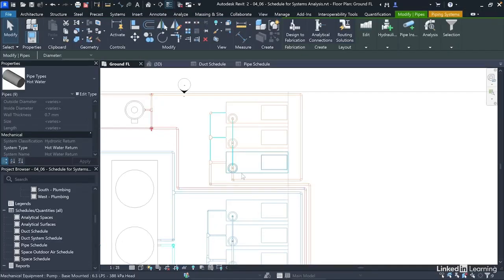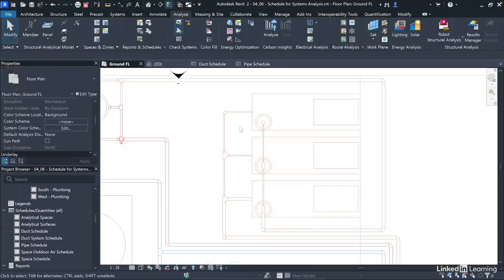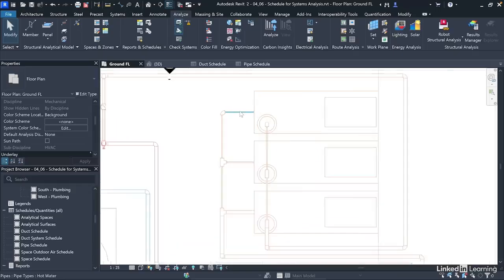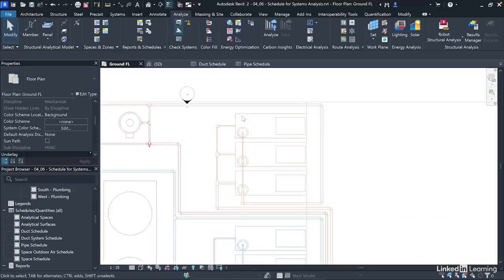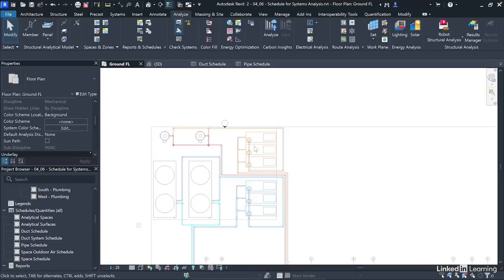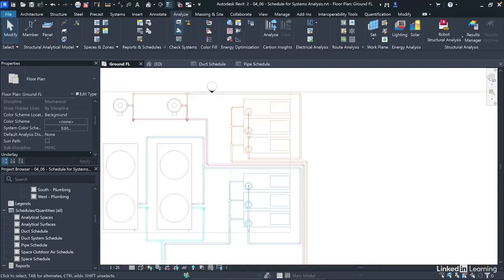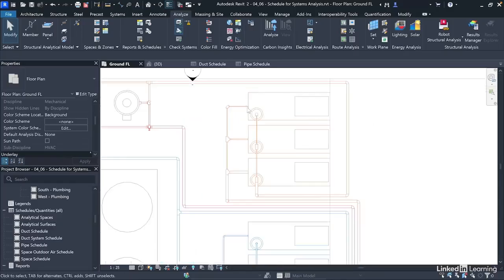So these are the kind of scenarios whereby, of course, in a real project, you have a lot of pipe accessories that can help you to increase the velocity of flow, and sometimes you might need to use this to resize the pumps and all that. But the bottom line of this is you can use your schedules to begin to dig into your design and begin to make improvements. So already we know that with this kind of scenario, we probably might have to increase our pumps or add a lot of accessories here to increase the velocity of water flow that is going through these pipes.